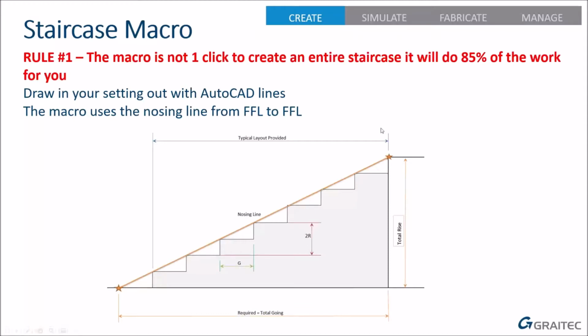So again, get the nosing points and the construction points correct, the rest will drop into place easily. But if you don't get these construction points right, you'll never get the right rise and going. And basically, easily putting in the angle is of little use. Okay, so let's have a look at that in action then.